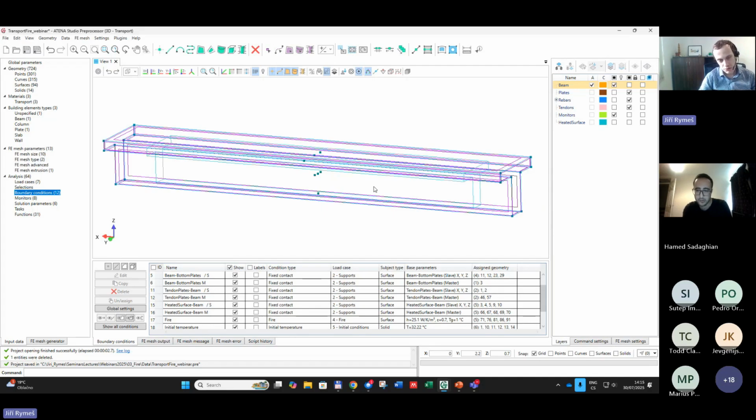One option which is possible would be to divide this overall volume into multiple segments, and then I will have a segment of 2 meters in length, and then I can apply the boundary function directly. However, now if I want to apply it for the 3 meters, it's not possible. I cannot define the boundary condition over some reduced length for the total surface.